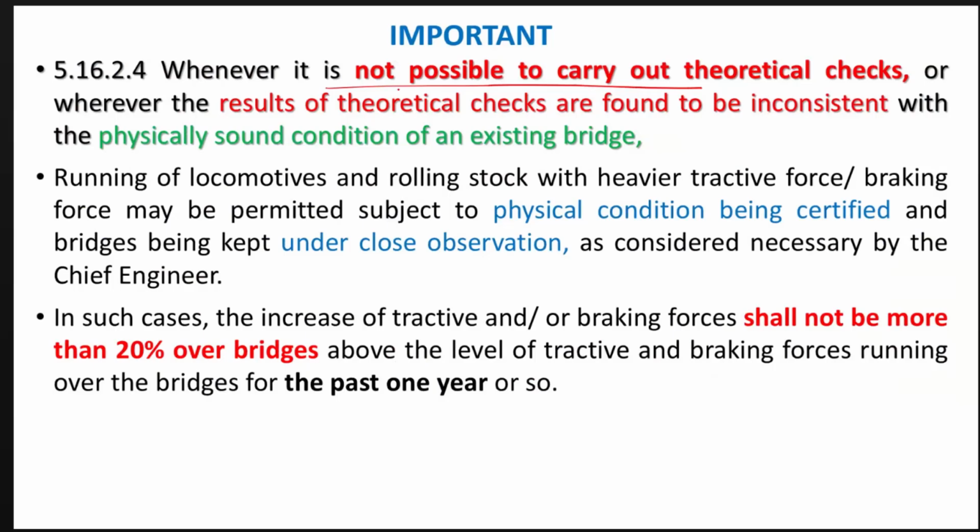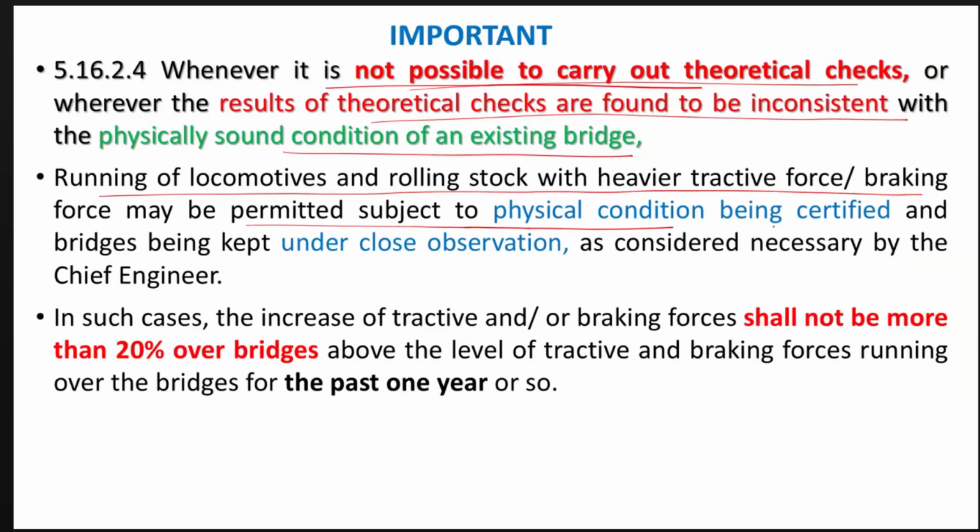So we will see where it is not possible to carry out the theoretical check, or wherever the results of the theoretical checks are found to be inconsistent with the physically sound condition of the existing bridge. Even if our loading standard is increased and the condition is sound, running of locomotives and loco stock with heavier tractive force and braking force may be permitted, subject to physical condition being certified and the bridge being kept under close observation as considered necessary by the chief engineer.